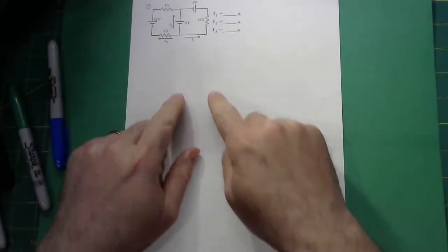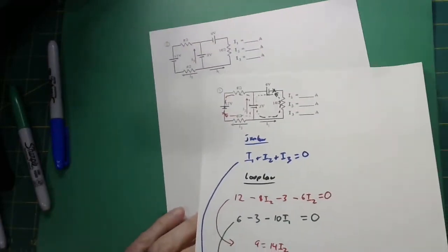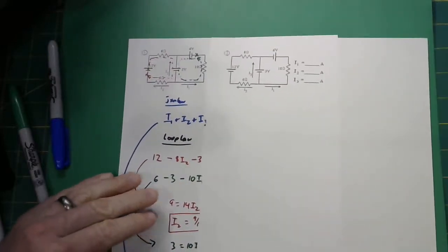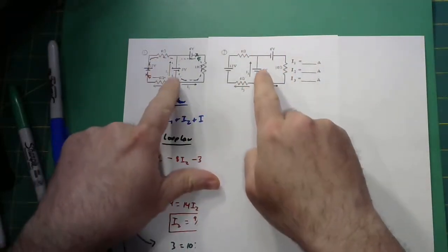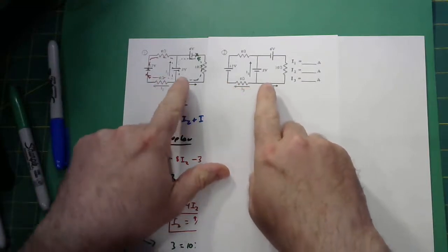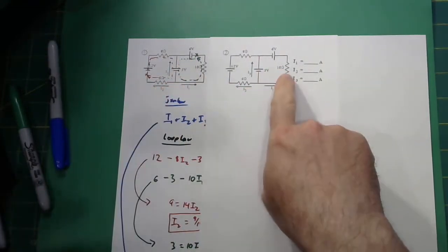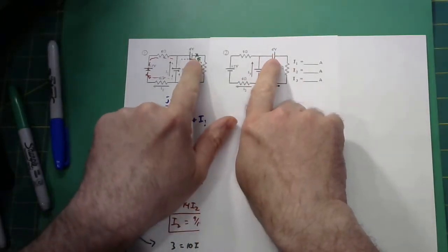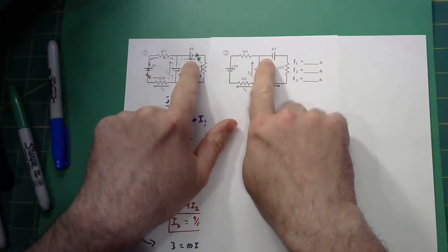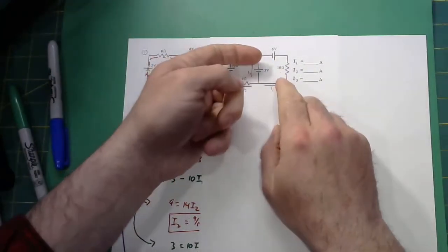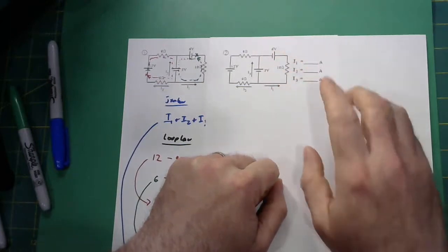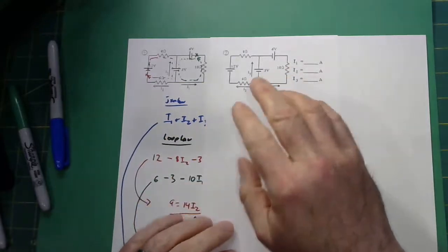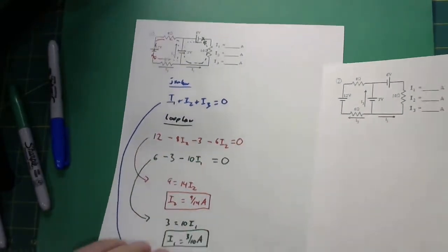Well, problem number 2. This one is kind of interesting to look at the diagram and compare it to the diagram from problem 1. And you say, hey, look, 8 ohm, 3 volts, 12 volts, 6 ohm, 6 volts, 10 ohm. Hey, it's the same circuit. There's only one little change. And that change is, look, they flipped this battery around. All right. So now the big 6 volt is trying to push current that way instead of that way. And so we're anticipating there are going to definitely be changes to the results we get. So we are not anticipating getting these same results out.